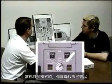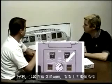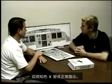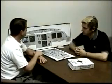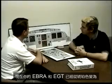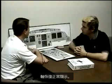What are some items you're looking for when you take the mode selector to ignition start? Well, I'm going to look on the engine page and look to see that the two top indicators go from amber X's to their normal indication. Anything on the lower display? The engine page will then show up.